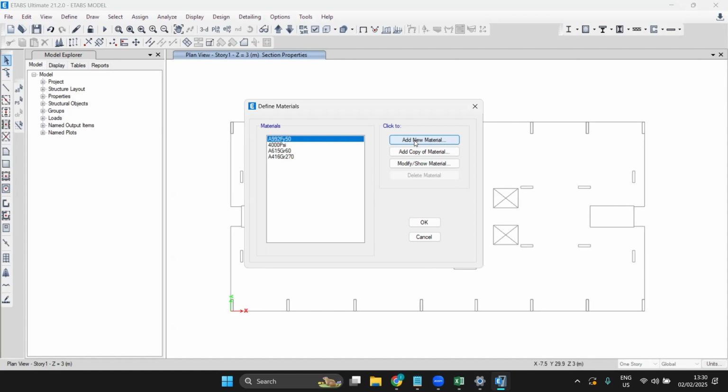Try to import to the basement. But before bringing it to the basement, create the number of stories. In the ETABS itself, create basement, story 1, story 2, story 3. Take it to story 1, story 2 or story 3. Then take this line to the basement. Then from story 1, delete only the slab edge lines. Keep the columns as they are.